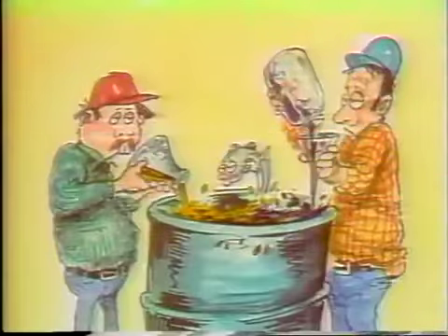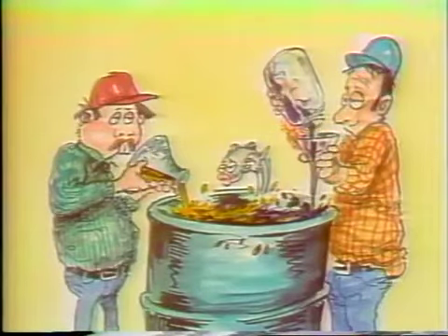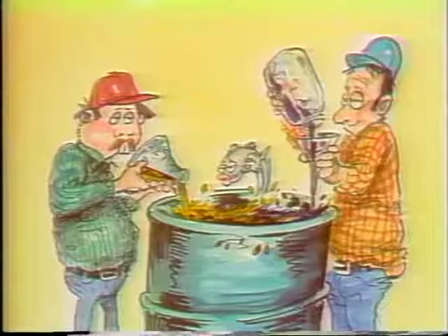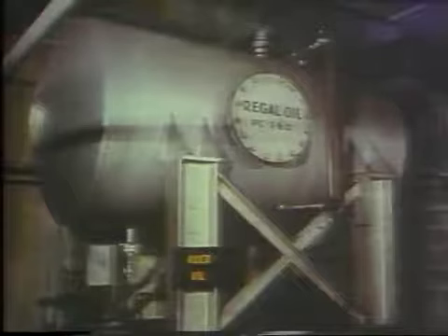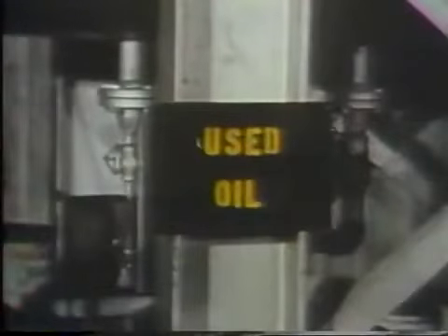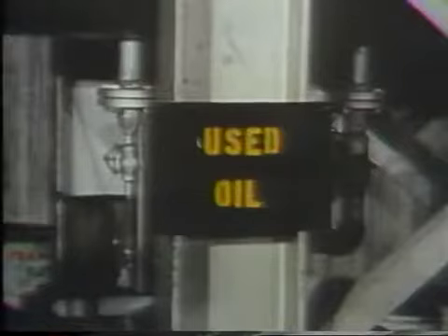After the vent is opened, lifting a spigot will allow the oil to flow. After oil has been drawn into the container that you're going to use, be sure to replace the vent cap. Otherwise, dirt could get into the barrel. Now, once you've removed oil from a barrel, never return it to its original container. If you do, you greatly increase the possibilities of contamination. Contaminated oil can cause serious problems because dirt and other particles could get into a bearing and scratch or otherwise damage its components. All contaminated lubricants should be clearly labeled and properly discarded or recycled.